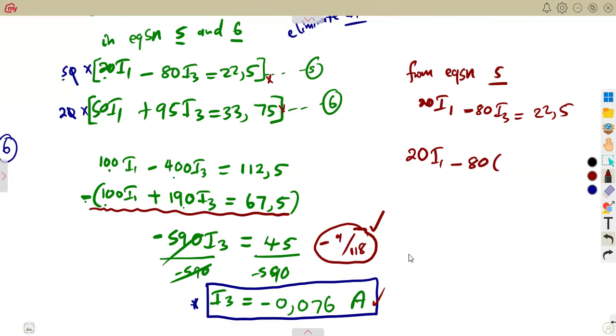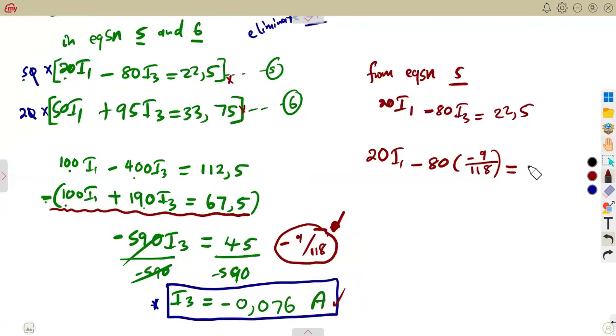But like I said, for exact values, because the way that we are calculating is different, try to just use a fraction so that at least your answers will be exact. If you are using a fraction, those are the exact answers that are supposed to be obtained. So do not worry when you're using a fraction. And like I said, when you're calculating any other current, you use it as a negative like that. Okay, so let's find I1. You can take this to the other side, it becomes a positive. You can simplify this. Now it's in your hands.